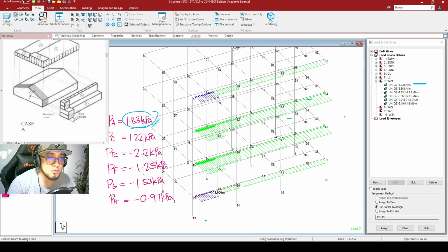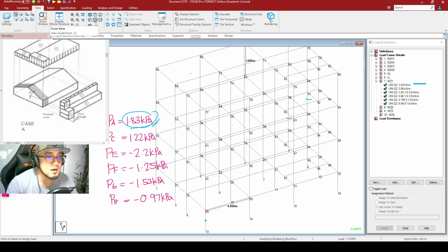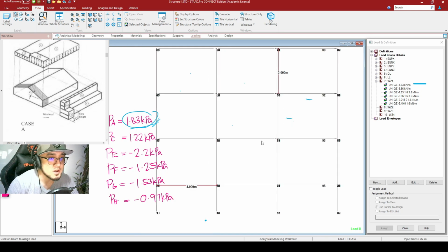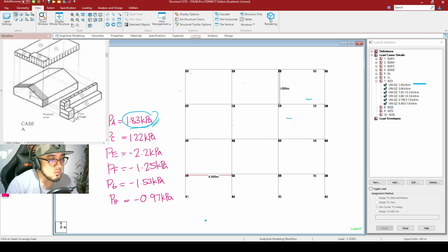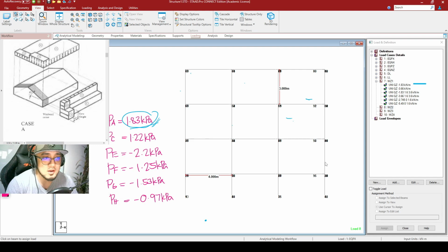But what about our wind load case number 2? For wind load case number 2, it is basically the reverse of wind load case number 1. So what do I mean there? Earlier we assumed that zone A of our member is located here, and zone C of our structure is located here. But this time, for our second load case, we would be locating our zone A at this portion right here, and we would now be assuming that zone C is located at this portion right here.